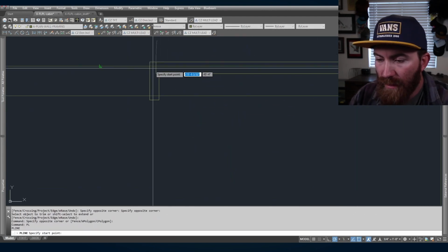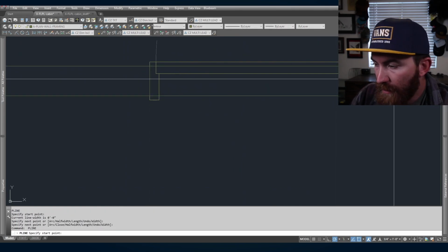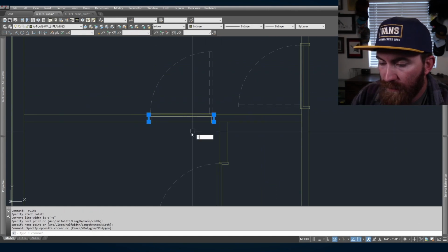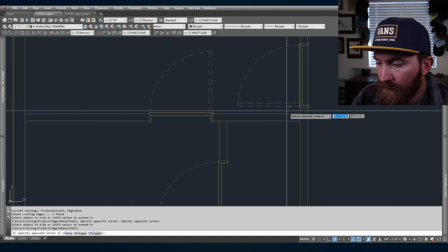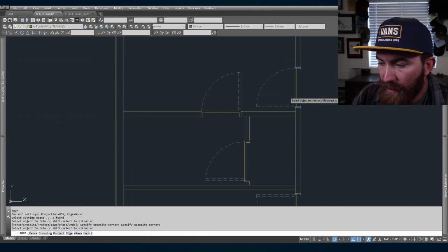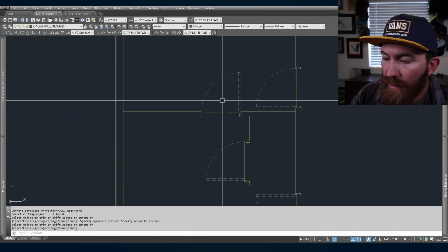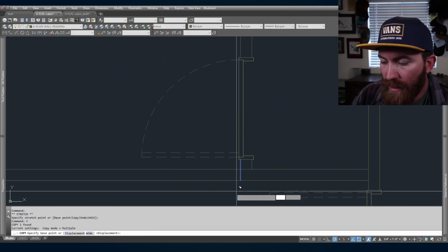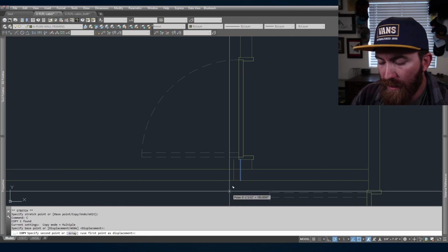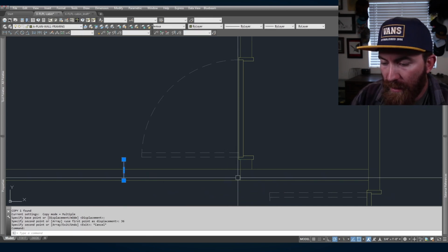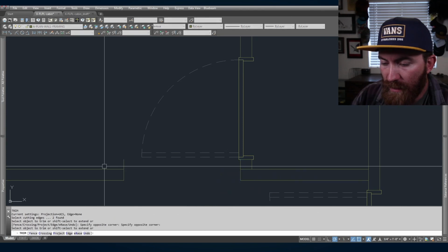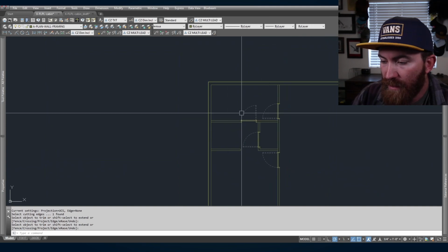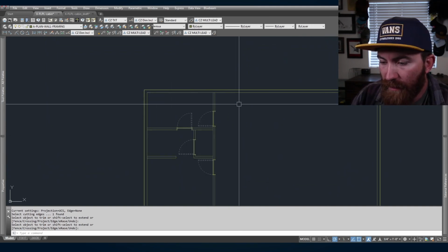Oops. Didn't put those polylines there, so now I'm gonna draw them. TR to trim, select across. See, this doesn't trim because it's in a block, so that is why that's occurring. Go ahead and copy 36 inches. And we're going to trim everything in between. Trim this, just makes life easier. There we go, it's starting to look like framing.